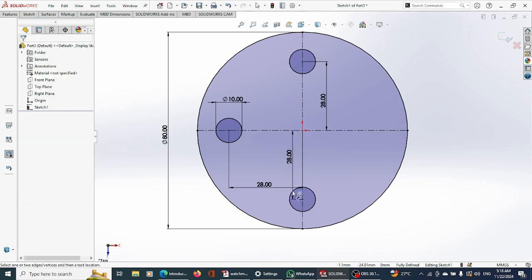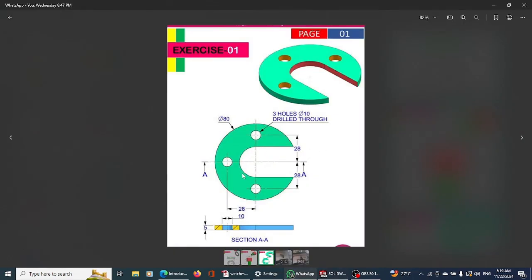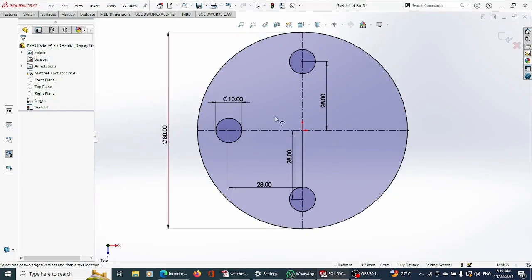Now our sketch is fully defined, but there's a problem. This guy, we need to cut it. You could use two features to draw this, but I don't want to confuse you guys. It's easier if we just cut it and then we just extrude. If we extrude like this, you can still go ahead and draw on the surface of what we extruded and then cut from there, but it's better if we just cut it here.